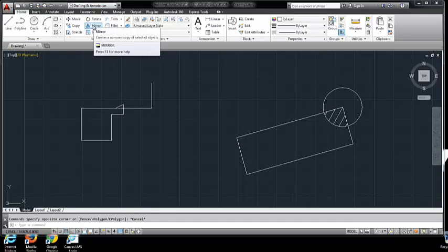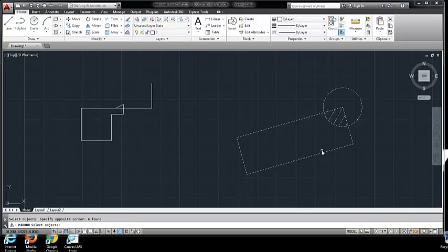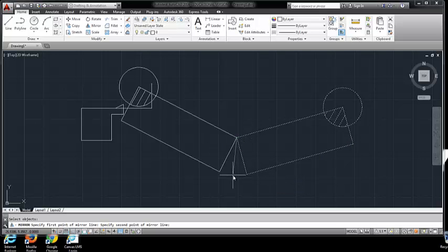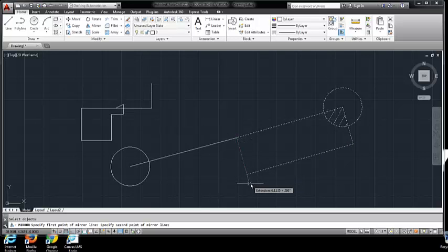So really fun command. We're kind of just giving you, if you want to mirror, kind of again the same thing. You're always going to want to crossing window, enter, so it knows where do you want to mirror it from. Let's mirror it from this corner. So we're going to mirror, and we're going to go, let's go negative 16.